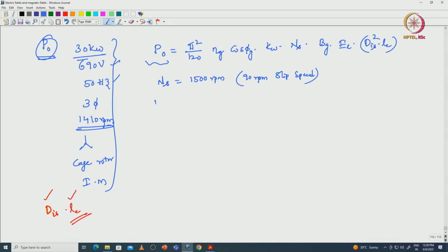Now, we have to assume the efficiency at the air gap, the power factor, and then the winding factor, magnetic loading and electric loading. All these variables are assumptions for the initial design to find the volume product. So, these many assumptions are there. If someone changes even a particular digit, the dimensions will automatically change.